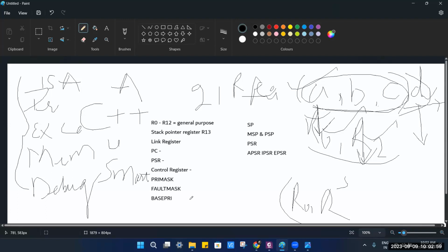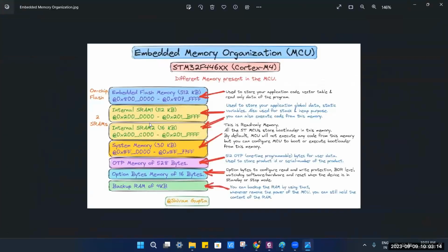Okay, I got your question. Bootloader and application program is there. One question: are all these things on-chip flash or a different one? They are on the flash memory of STM32. Like I will say 0x8000 is the address for the bootloader. Then you have got 32 KB allocated for the bootloader. Then at 0x8040000, you have got the application program reset handler.